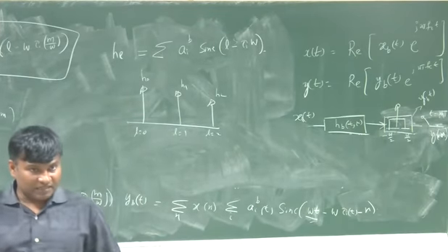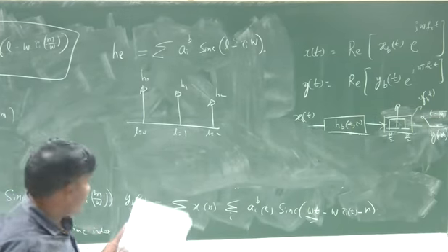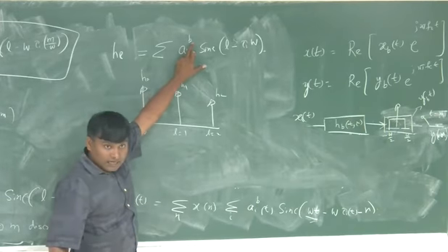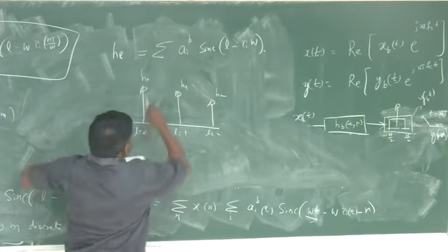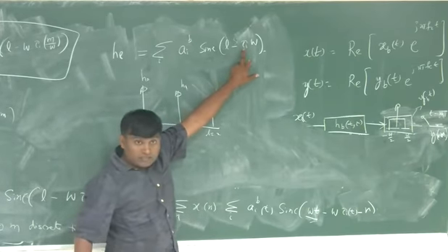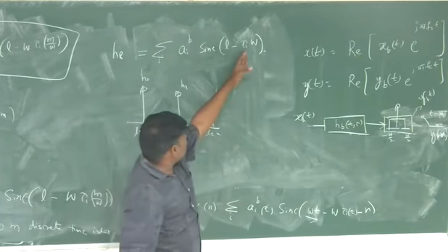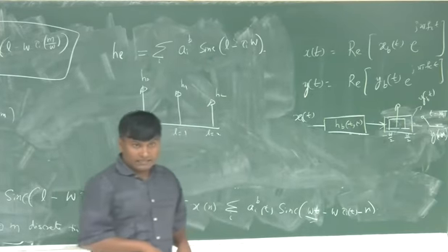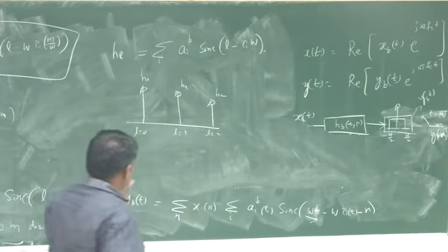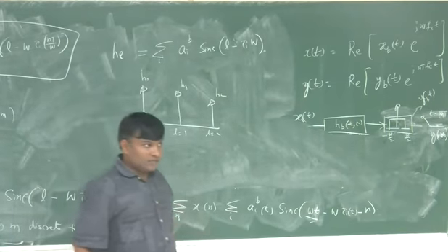You can start with any L. It is a function of a_i e to the power of j 2 pi theta_i, indices i, tau_i, and they are a function of the product tau_i into W. Tau_i into W is tau_i by T. So you are going to resolve a T-spaced equivalent channel from the original channel.